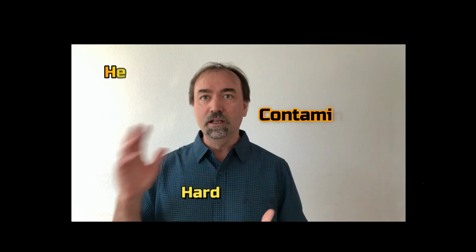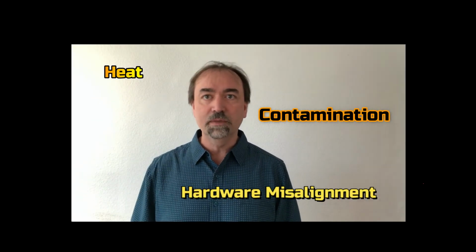So what kind of PV are we looking for? Choosing a seal just based on the PV value is not an exact science. There's other things like heat, contamination, hardware misalignment that will ultimately change our decision. In general, a PV of 100,000 is a baseline for success for a positive contact PTFE lip seal. It's possible to go as high as 200,000 PV, but more discussion is required with our engineering staff.